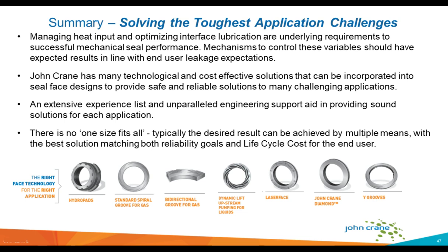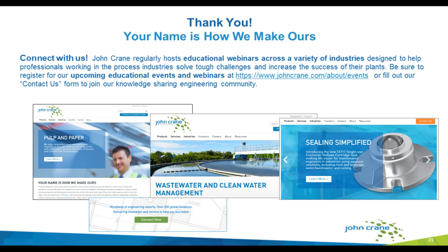Well, in reality, what do we mean by a seal support system? Every mechanical seal, apart from a mechanical seal that's fitted in a pump with API Plan 02, which is dead-ended, can be considered a seal support system. A pipe coming from discharge into the seal itself is a seal support system. So in reality, it depends on the application and what system you require for seal flushing, whether a single seal or a dual seal. Again, the only non-system that exists out there is Plan 02.